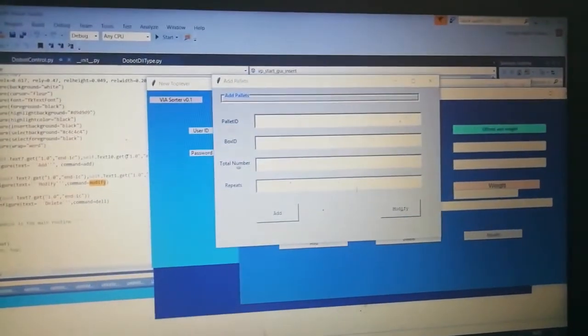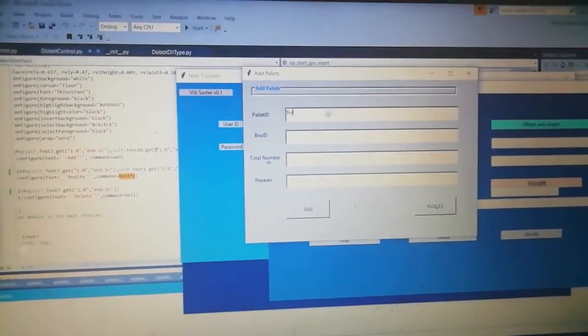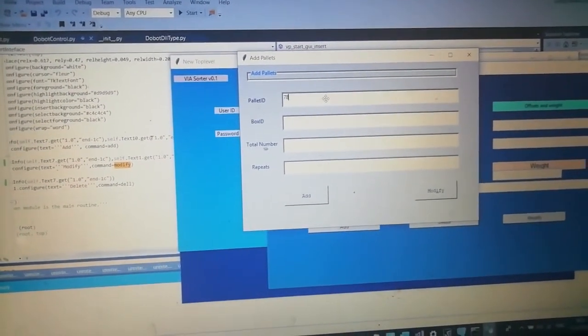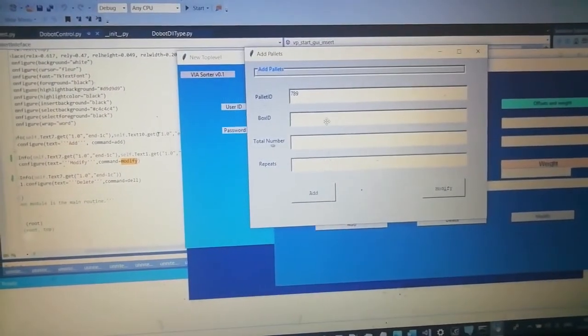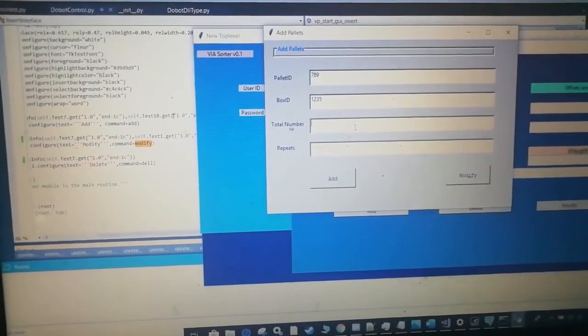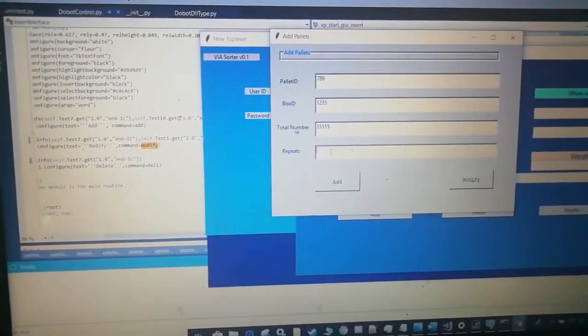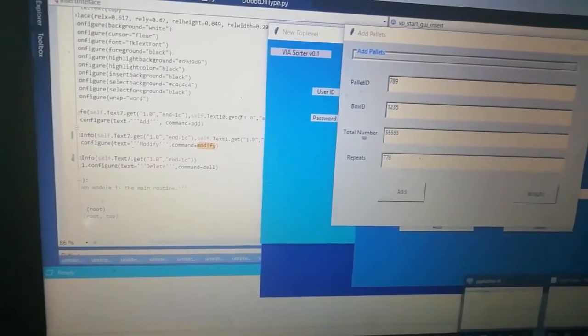The Dobot robot made the development process more convenient. However, it brought some problems to deal with as well. The connection between the robot arm and the computer is unfortunately not consistent. The connection between the robot arm system and the computer was indeterministic, and changing the configurations did not help. The team wasn't able to determine the exact cause of the connectivity error, but an educated guess based on observation has been made that it's from hardware connection issues.